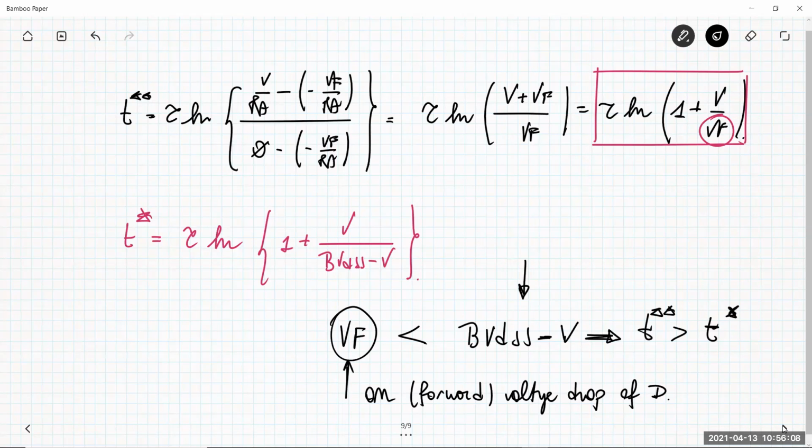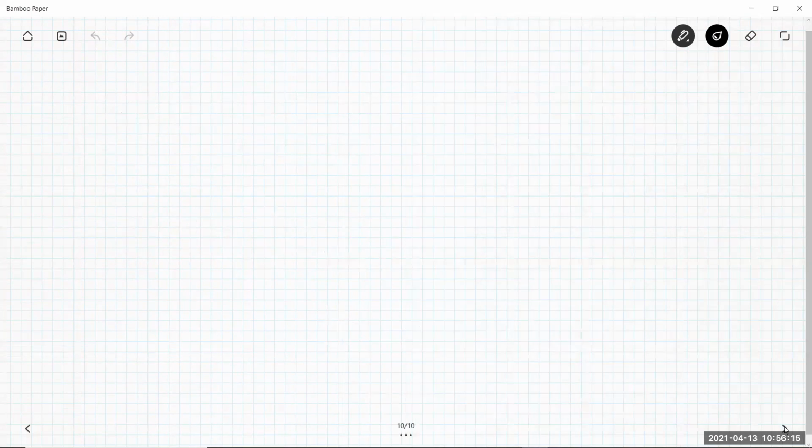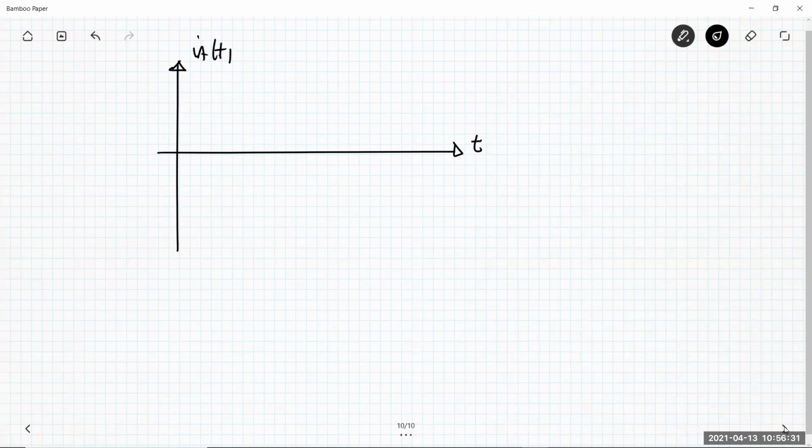Okay, so we add a freewheeling diode, and we solve the problem of having a MOSFET, as a switch, operating into its breakdown region. That is always something which is not very safe, let me say. But anyway, we have the problem of having a turn-off time which is larger than you can have before.